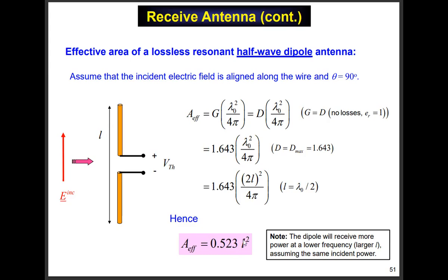One half its length squared. So if it's got a length L, think of generating a square L by L, okay? And then the effective area is roughly that cut in half, okay? Now notice, this may or may not be obvious to you, but let me make an important point here. For a general arbitrary antenna, effective area has nothing to do with the physical area of the antenna.